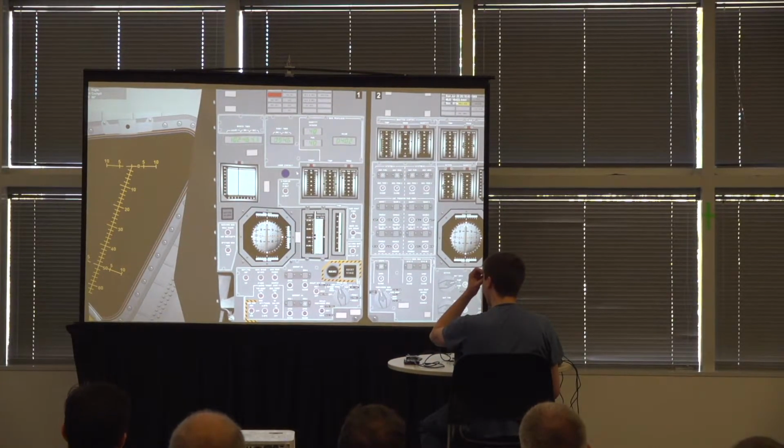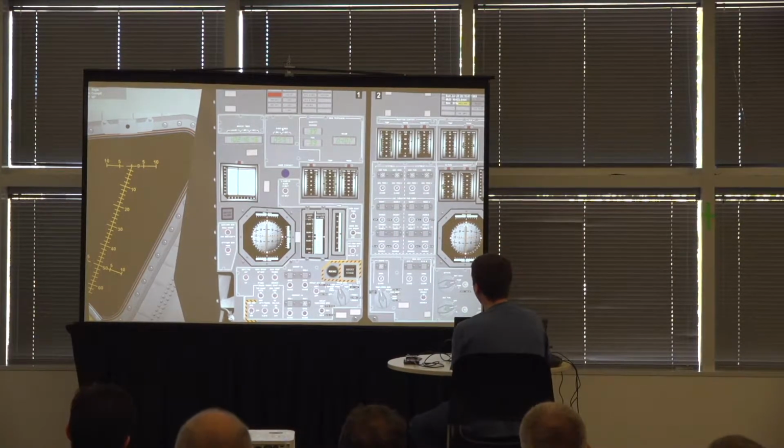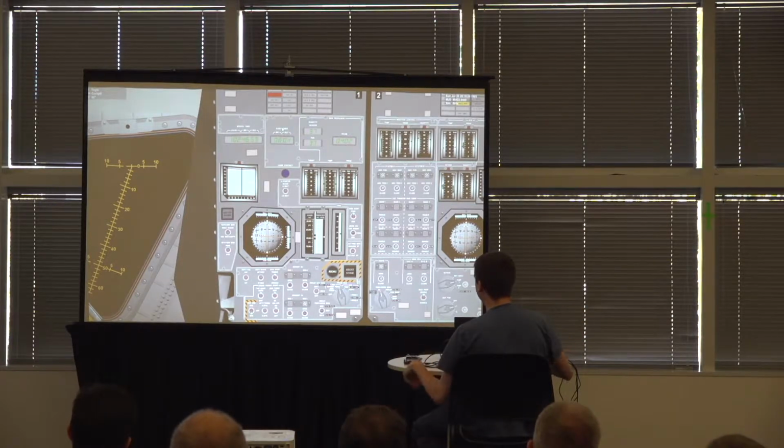The next event that's coming up is ignition plus 6 minutes and 45 seconds. And that is when our descent engine should throttle down. The descent engine is not stable at throttle settings between 60% or so and 97%. So throughout this entire landing, we've been flying at 97% throttle. As soon as the guidance for the AGC wants less than about 67%, the throttle is going to snap down to that. It happens at a very predictable time during the landing, and if it happens on time, it means that you're on a good trajectory.